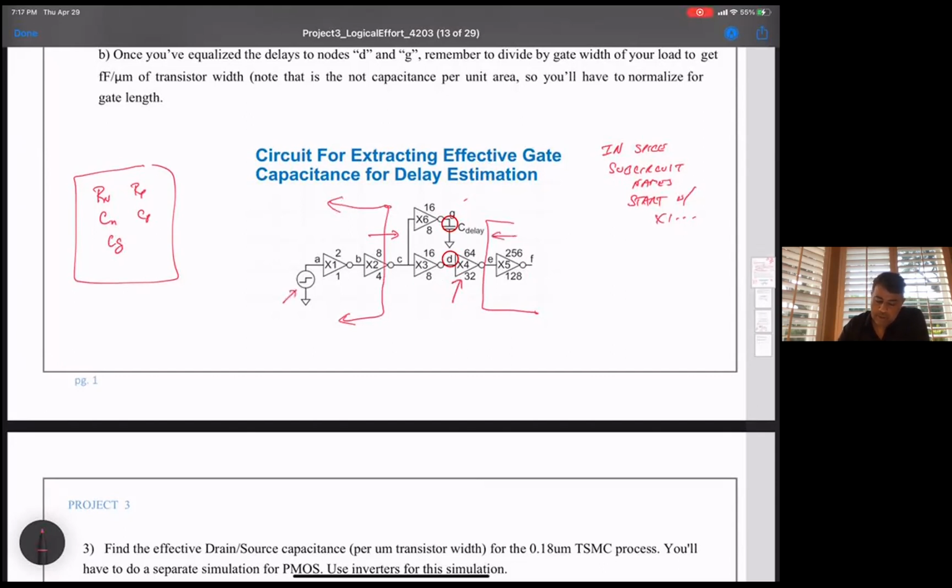So you can do crazy stuff here. You can say my input voltage has a rise time of a picosecond and a fall time of a picosecond, etc. That's fine, from 0 to 1.8 volts. But as you go through this guy, and as you go through that guy, they'll impose their own rise and fall times and pulse shapes on the pulse. So by the time you get here, you'll have a reasonable pulse shape and rise and fall times.